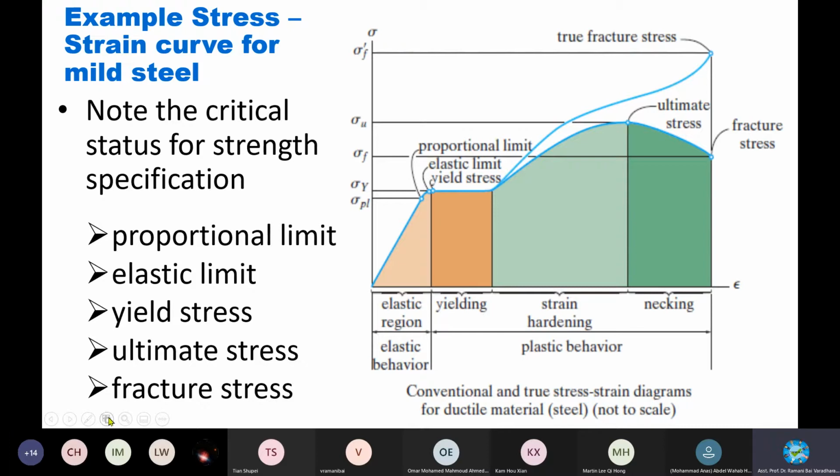I take the laser pointer. This region is a very dangerous zone. The engineer in charge in the company, for tools and machines, should notice that the material is still working but has started necking, started going to fail. This is the region where you have to take action, the time given to replace or stop the work, to avoid any dangerous failure or hazard at the end.